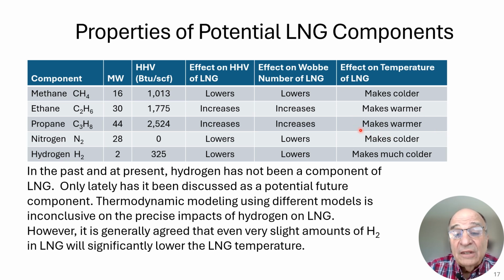That's because, you recall, propane has a boiling temperature of somewhere around minus 40 degrees at atmospheric pressure, and I say somewhere around minus 40 degrees, depending upon what atmospheric pressure is. At 14.73, it might be minus 44 degrees Fahrenheit, but we measured it at 16.5 psi absolute, and that came out to minus 39 degrees Fahrenheit.